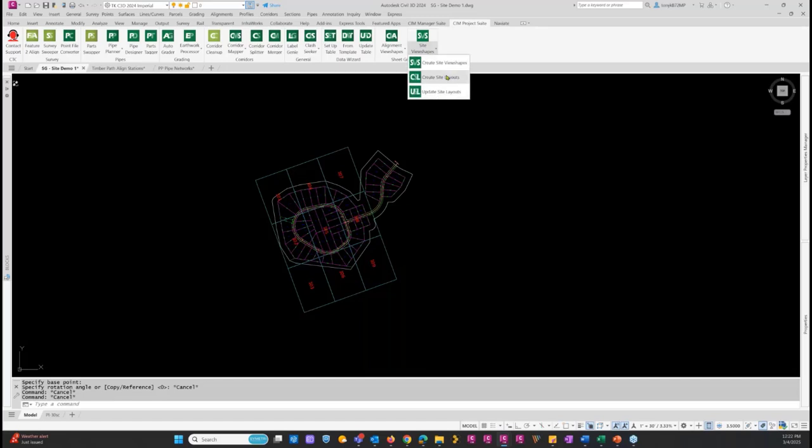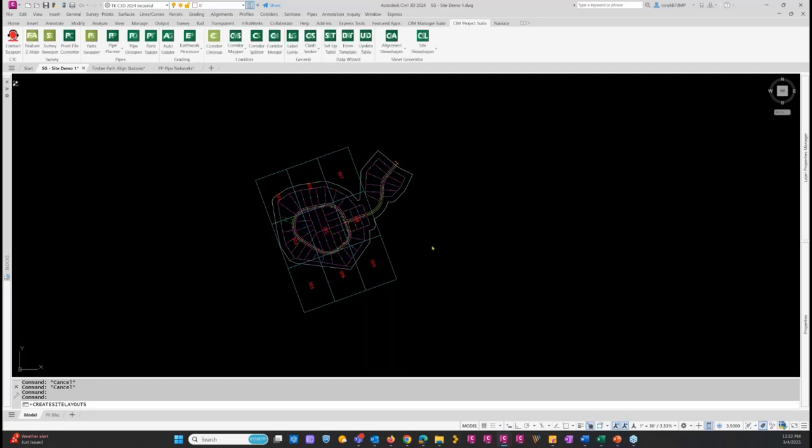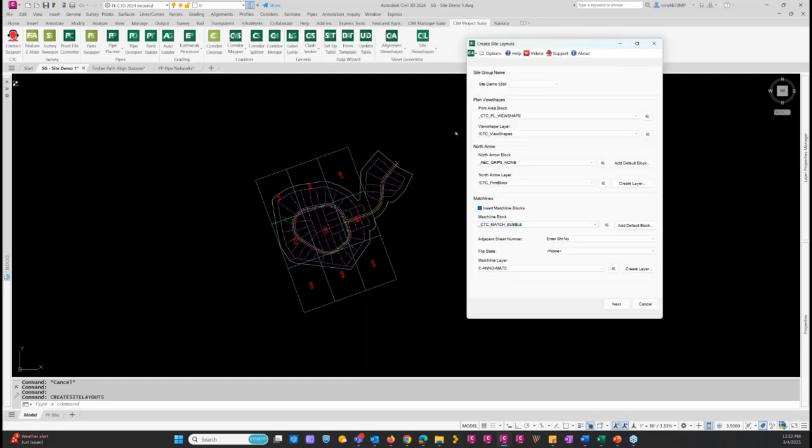Then to create the layouts, it's simply going right down, top to bottom. Same as with the alignment, it's going to give us the standard AutoCAD there. So then if I had different groups in here too, I would go ahead and select a different group, which we would have named and created in the create layouts, and it knows by group everything I'm using here. So it already recognizes that, so I won't have to go back and pick those. If for whatever reason you need to, you can do the pull down again or go pick in the drawing.